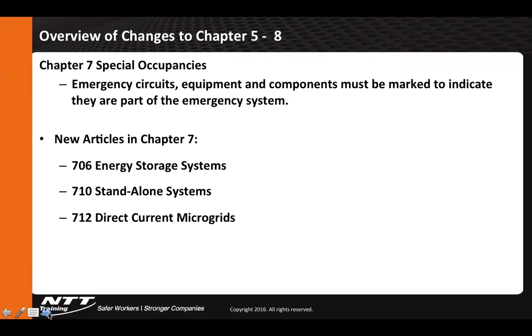And another issue that I'm a big fan of this change is in 408.3. You know how it is, okay? Now, I'm not going to raise my hand, but anyway, you open up that main service panel, and even if you shut the main breaker off, you're still exposed to those main terminals coming in, even though you've killed the power down below on your branch circuits, and so now you're going to put a new branch circuit receptacle in there, or replace one or whatever. So now there's going to be a requirement that those main terminals be guarded, so that once you shut that main breaker off and you verify that the bus bars down below are de-energized, then you can go ahead and work on them as de-energized equipment. So I think that's a good positive change in 408.3.